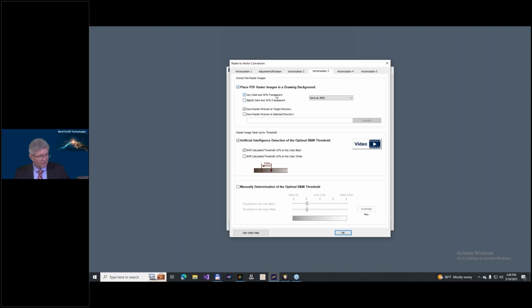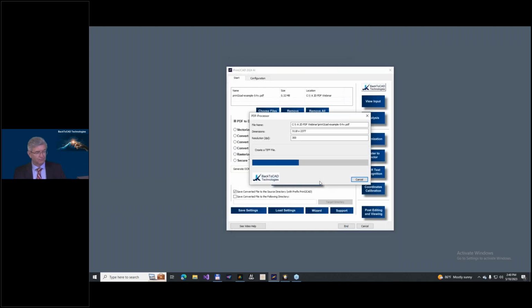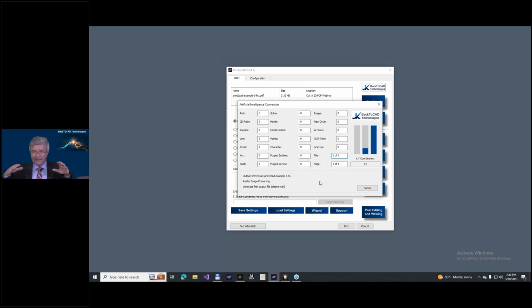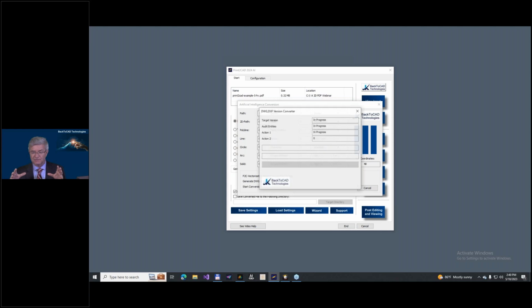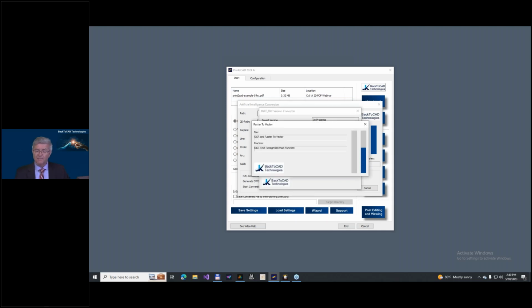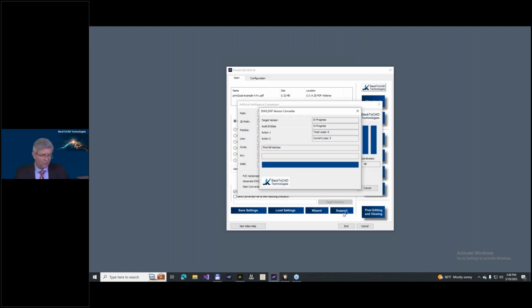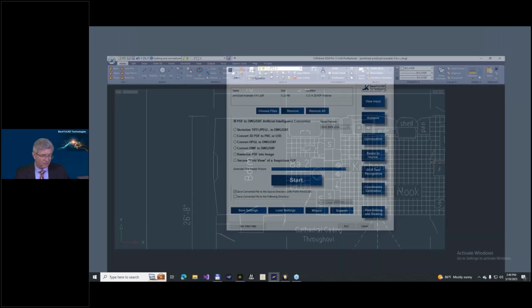We make it dark and 30% transparent, because then you can correct errors and see the quality of the conversion. This is what I recommend every time. Simply put this raster picture in the background so that you can see how the conversion is working.